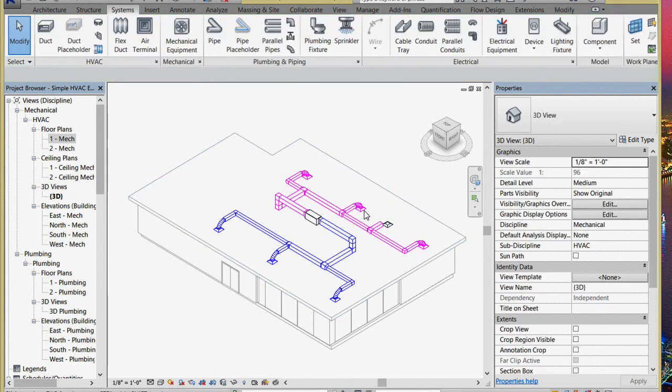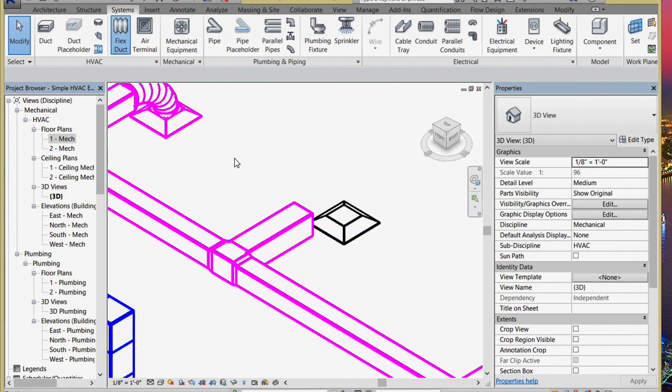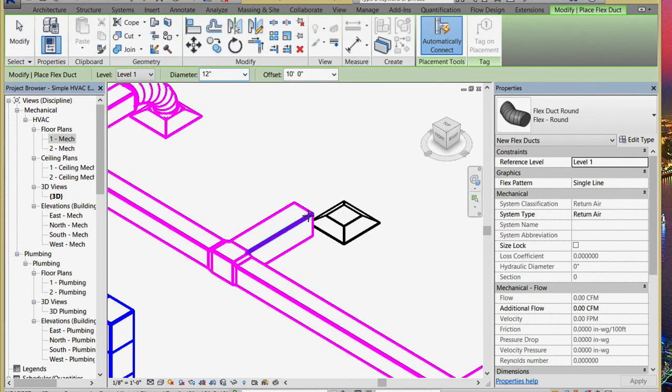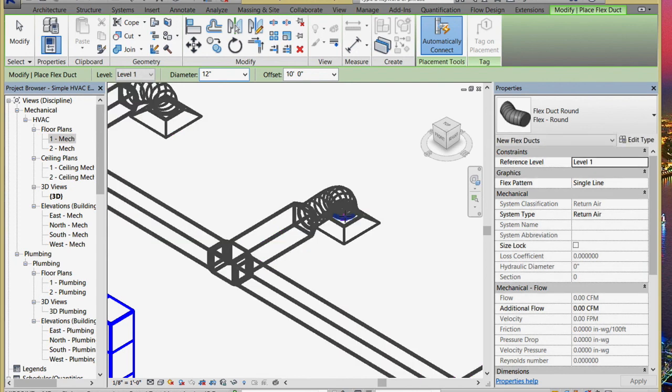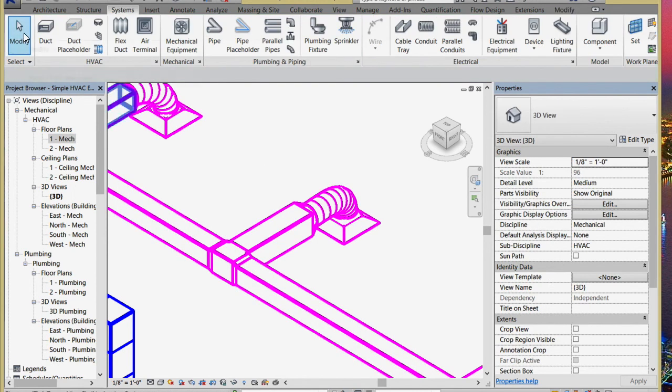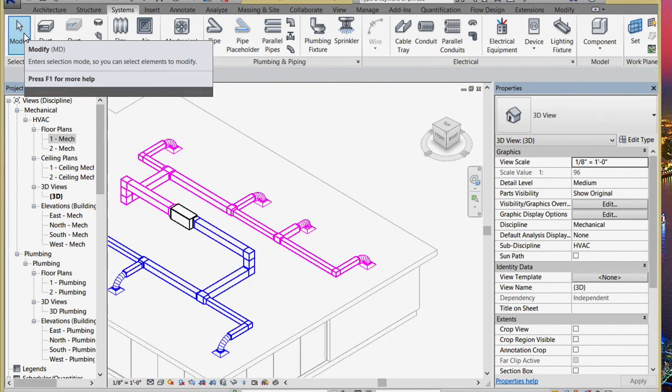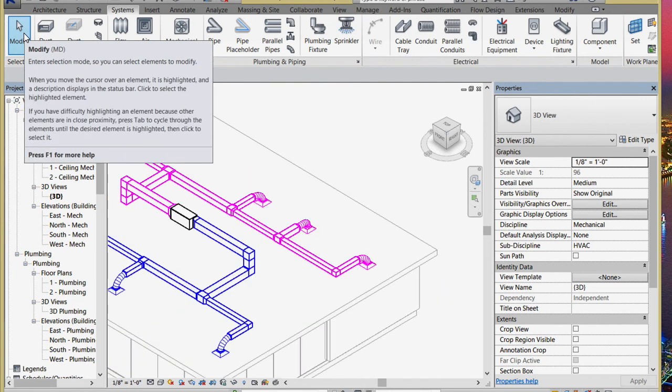Now it does. And the final thing is I should put a little piece of flexi duct in here, so the system will be a little bit better. Okay, we need to do something similar on the return side too, or the supply side, so that we can pair them and have them balanced.